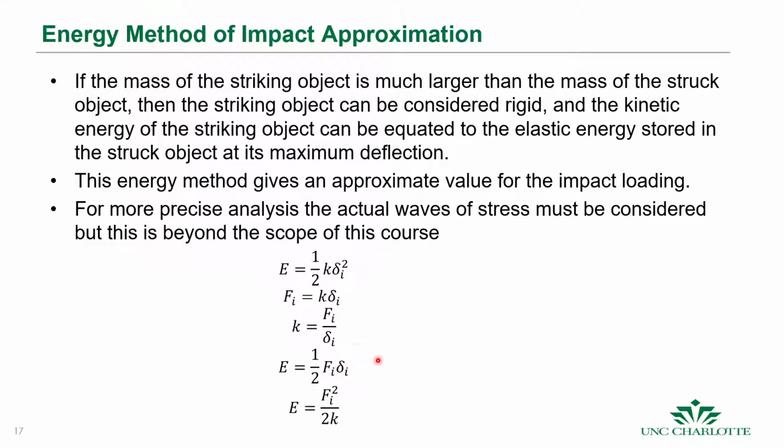So if you looked at a force displacement curve, you could just take half of that area that's traversed, which would be the triangle of that force displacement, and that's the energy, the elastic energy that's stored in that spring or in that structure, which is really a spring that deflects delta. Okay, and it's important to think of structures as also springs with stiffness.